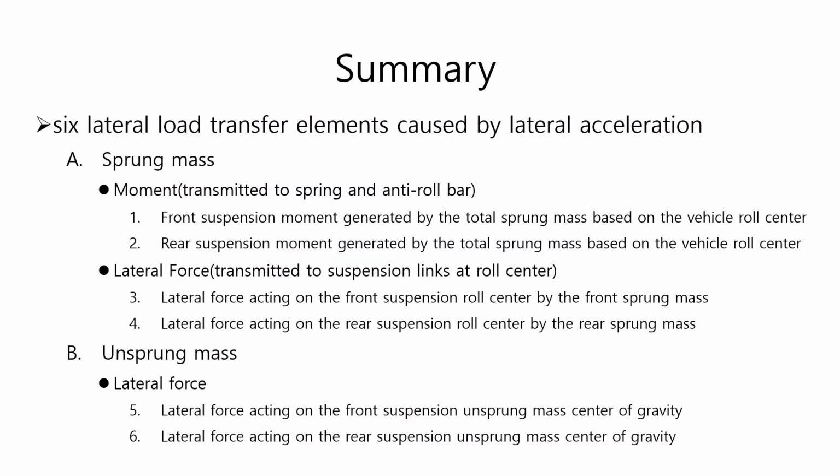Let's summarize the contents of this video. I explained how to calculate the 6 lateral load transfer elements caused by lateral acceleration. When the concept of the roll center is introduced to analyze the lateral load transfer, the force generated by the lateral acceleration at the center of gravity of the sprung mass is divided into the force transmitted to the spring and anti-roll bar in the form of a moment, and the force acting laterally on the roll center and transmitted